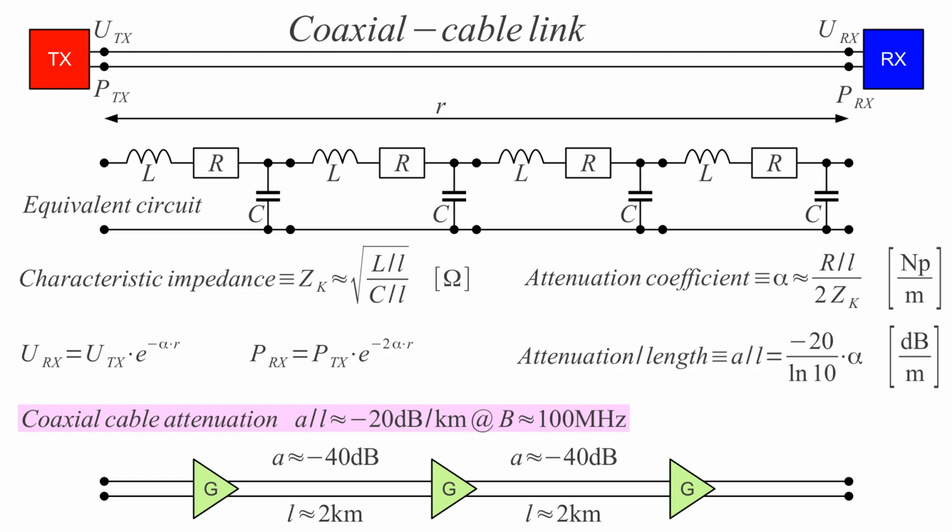The equivalent circuit of a coaxial cable applies to any two-wire link, maybe a twisted pair besides coaxial cable, maybe another metal line, maybe shielded twisted pair. Any such electrical connection has a series inductivity and a parallel capacitance, and has losses.